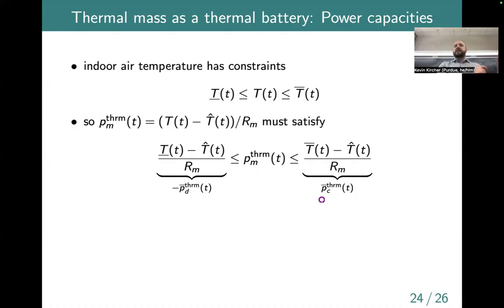Okay, yeah. So the idea here is that over time we could heat up the thermal mass, and then what might happen is some of that stored heat would bleed back into the air, and then we'd warm up the indoor air. And then, if you were to change to a different model, would you want to add more resistors, more capacitors to model that?